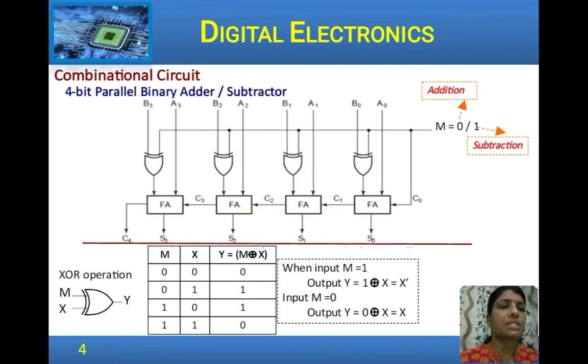Now, when M is 1, that is, 1 is given to one of the input lines of each of the XOR gates, the output is X bar, the complement of the input. So, what we get as the output is B0', B1', B2' and B3' over here. And this line is 1, and that is given as the carry input to the first stage. So, effectively the 2's complement of the number has been obtained. The adder circuit is used to perform subtraction. So, we have used a single adder circuit to perform both addition and subtraction.